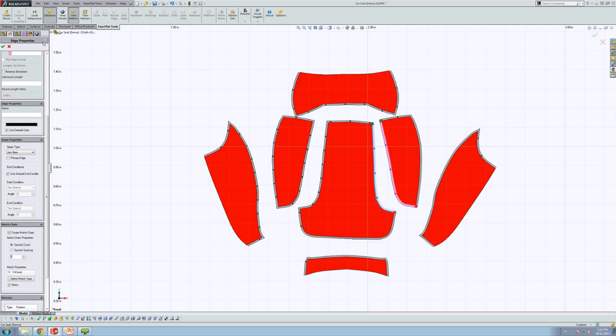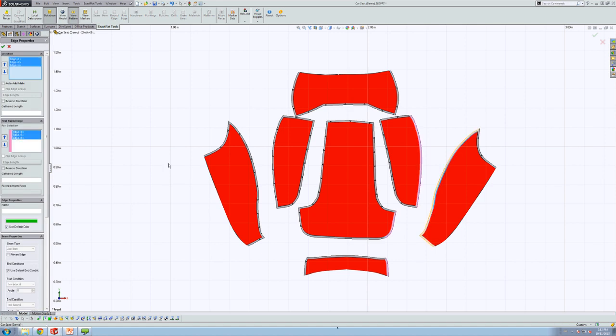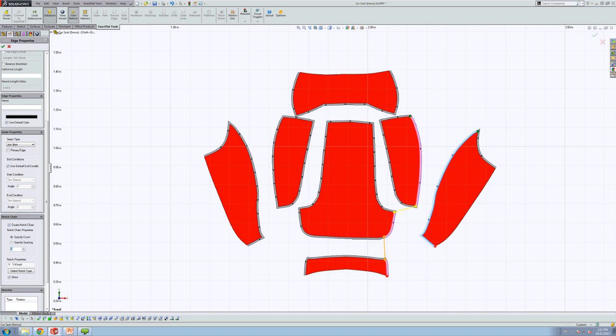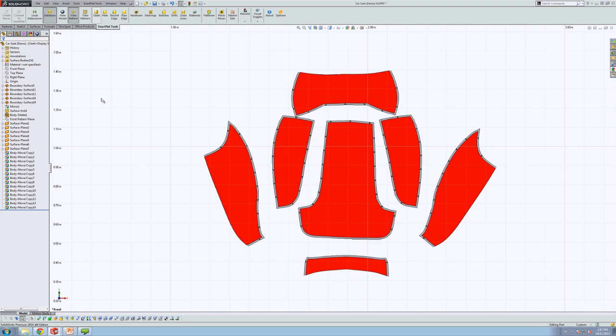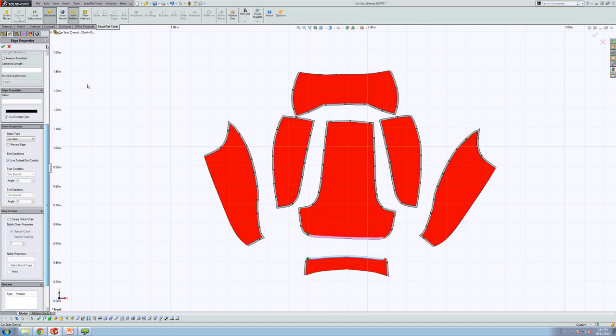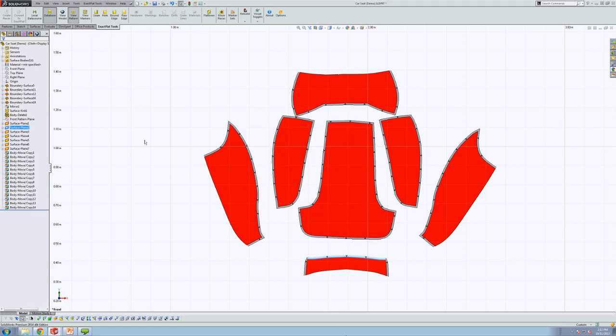So for example, if you took this car seat and you said, it has to be 5 millimeters longer for whatever design criteria you might have. If you build your model parametrically, you could update that model, and then you could actually go in and change the notches. And if you specified a certain number of notches within the length, that would update automatically as well. So the advantage of having these features applied through a database is very, very strong. And what we're trying to do here is apply principles that are very similar to lean manufacturing to lean design, and that would be no waste and no waiting. So here we have our pieces already notched up.